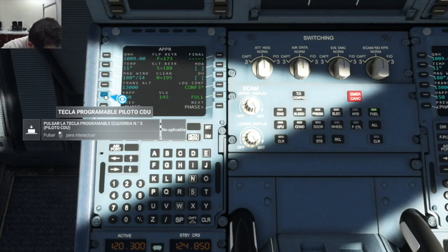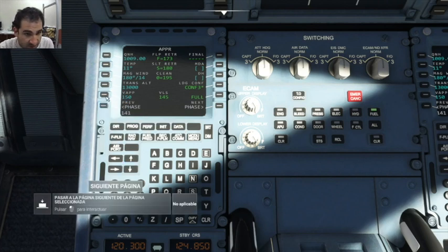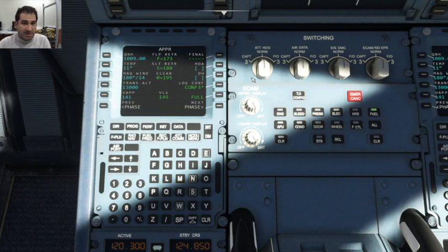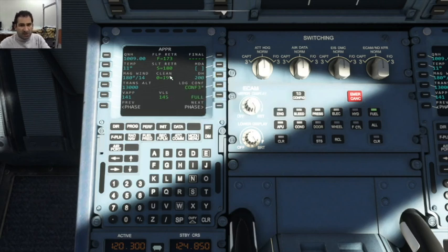and the approach velocity, which is in the operational flight plan, let me grab it, is 141, right, in our operational flight plan, so we can include it here as a reference. Okay, here we could include the minima decision height, maybe is 200 feet. Okay, we're going to fly an ILS approach,